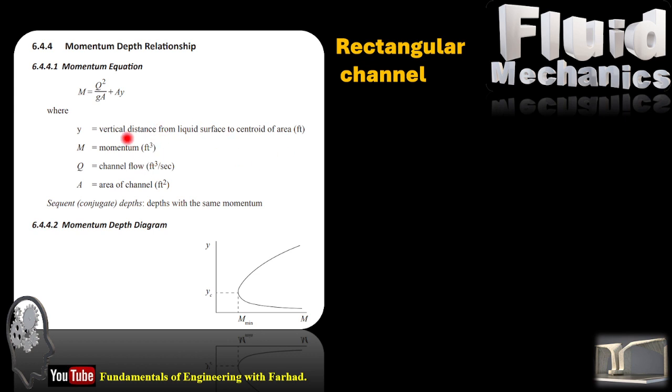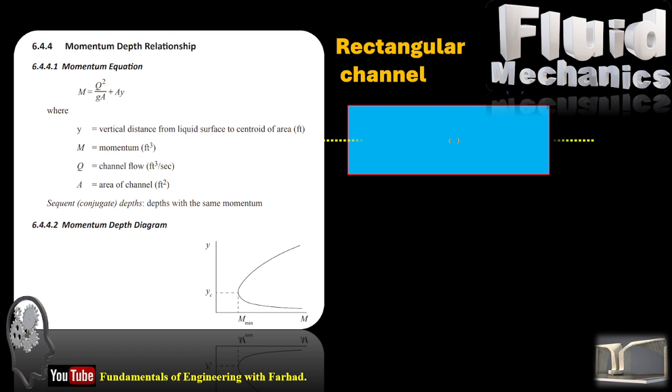If you move to a simple case like a rectangular channel, which is most of the cases, like our problem, you can easily see this is y, the height of water, and half of that goes to the centroid. We call that a half of y. If you make it simpler, you get Q squared over g y plus half of y squared.